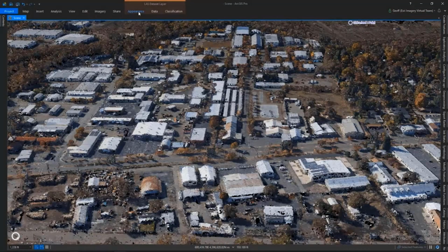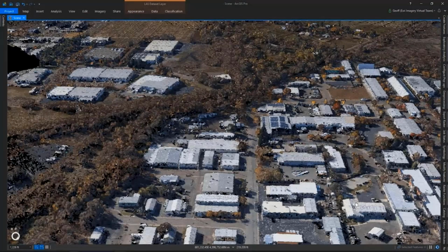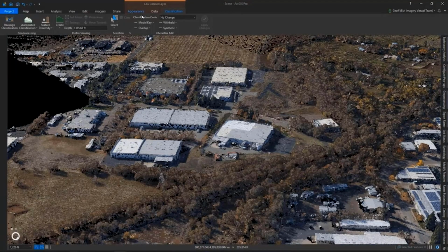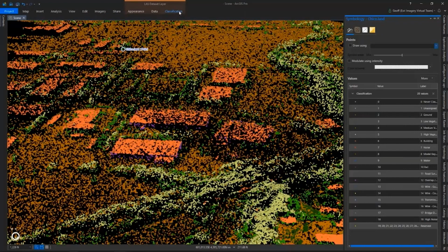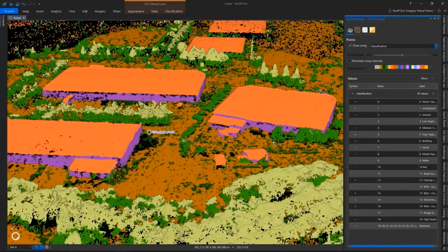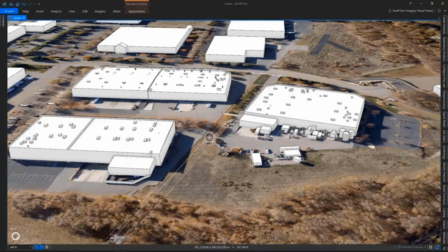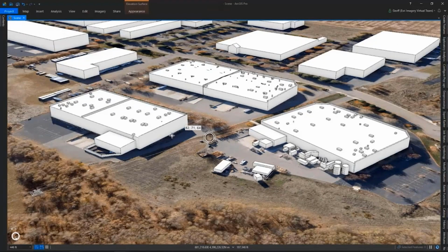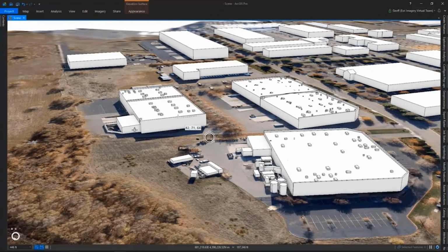We can even add the LiDAR point cloud data. In this case for drones, it contains color values automatically. And Esri provides a suite of tools to help support classifying this data. With point cloud, you can visualize and switch between different ways of rendering using symbology. And as we see here, we can manually improve and update certain building or feature classifications using tools in ArcGIS Pro. And lastly, we also provide a suite of tools that allow you to convert the point cloud data into 3D models and even manually improve certain components of buildings directly from LiDAR and drone-based point cloud data.